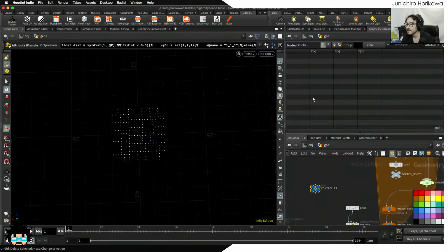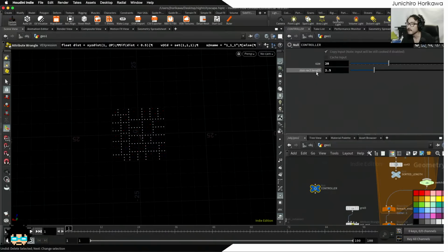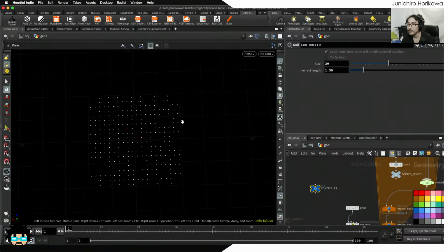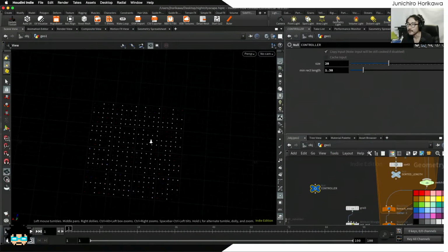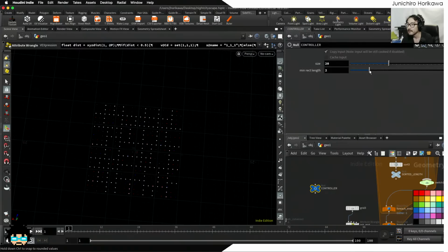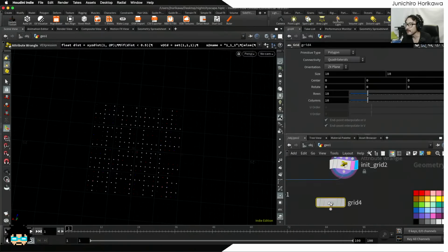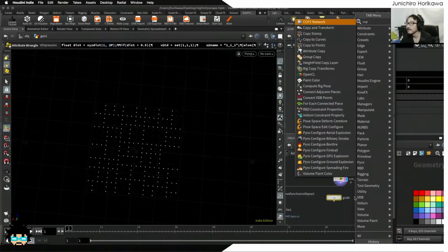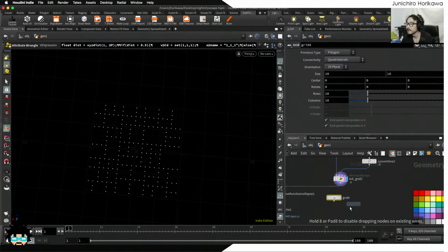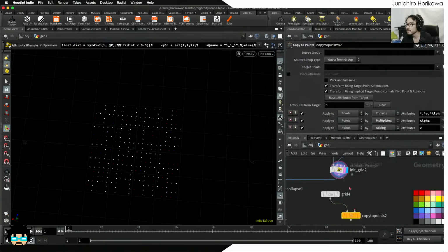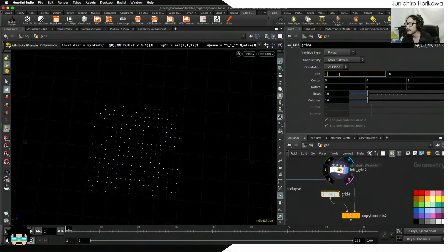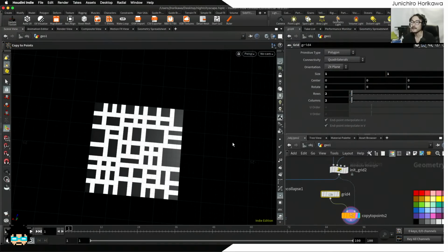And let's set some parameters, like set the minimum leg length to smaller, like having a lot of grid openings like these. Okay, and it's a bit hard to see what's going on here, so I would like to create a visual guide with the rectangle, and set the grid size to 1 by 1, grid 2 by 2, so that it's easy to see what's going on here.